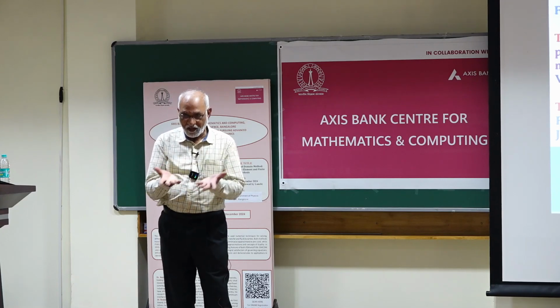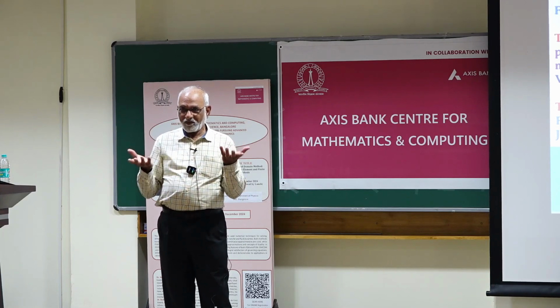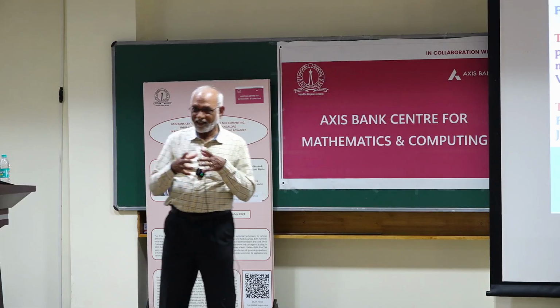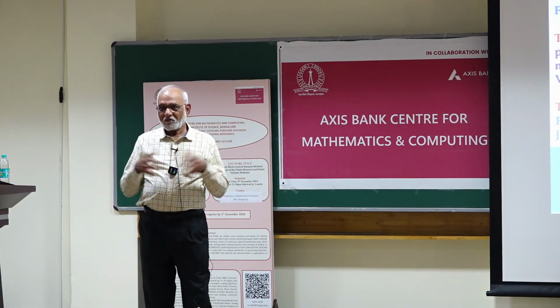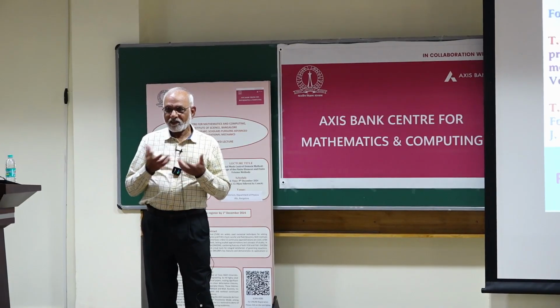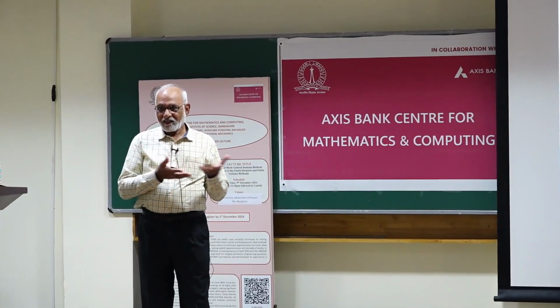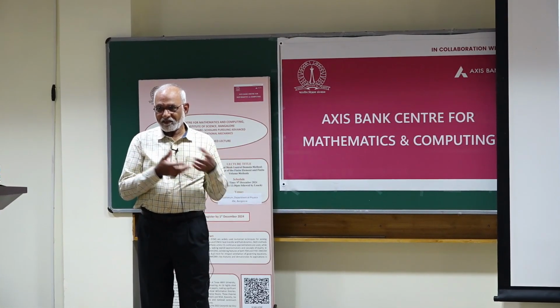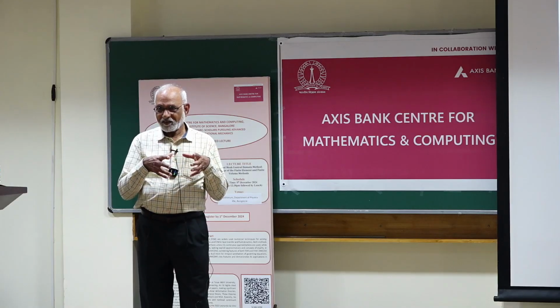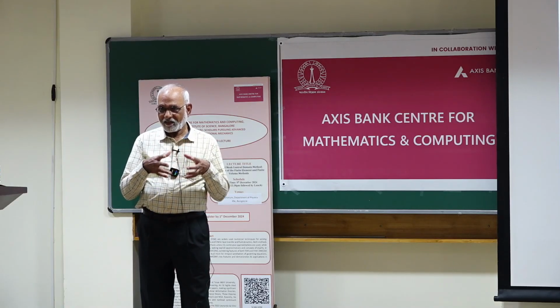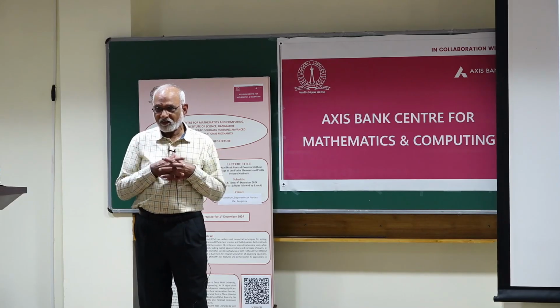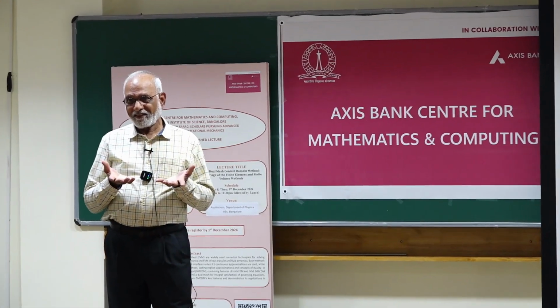Same with carbon nanotubes: people use shell theories, cylindrical, but all of these are continuum theories, whereas a carbon nanotube is all atom interaction, right? Potentials. So really you should use molecular dynamics.